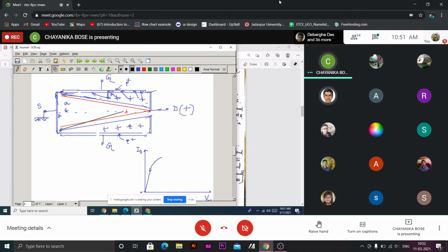I understood the pinch-off, but I did not understand the part about the positive 5 volt at the earlier point. Yes, the expression for the pinch-off voltage is qND a squared over 2 epsilon, so depending on the manufacturing, a particular junction field-effect transistor will have a particular pinch-off voltage. What does that imply? It is the reverse bias appearing across the N-type channel and P plus gate, for which the depletion width Wx will be just A, the half width of our channel.